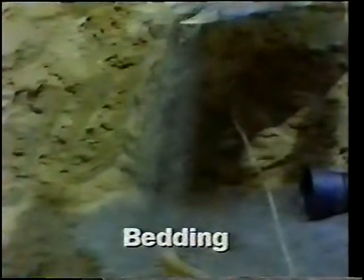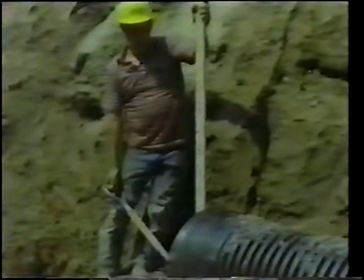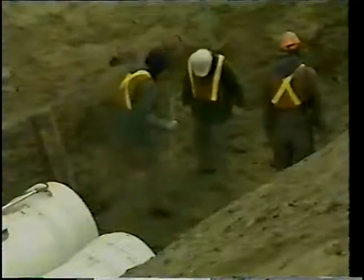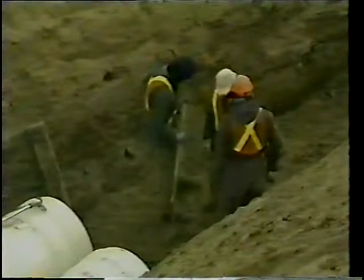Bedding supports the pipe, distributes the load on the bottom, and should maintain the grade for gravity lines. The bedding thickness depends on pipe type and diameter. In the past, bedding was compacted, but now more and more organizations are recommending that the bedding be placed loose for a few inches so that it cradles the pipe.